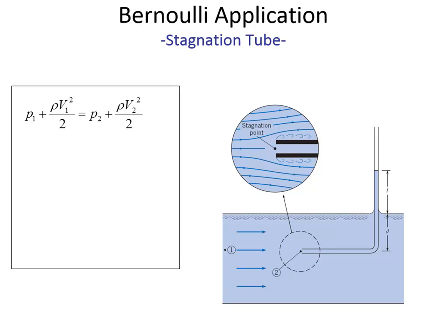Stagnation was at the heart of that last example. The idea that if you have a streamline going along, that means that the water has velocity. There's energy in that velocity. But then all of a sudden, that streamline stops. That means that there's going to be a loss of the energy that was in kinetic, and it's going to have to go somewhere. And it's going to go into a localized increase in pressure. That's what happens with a submarine, for example.